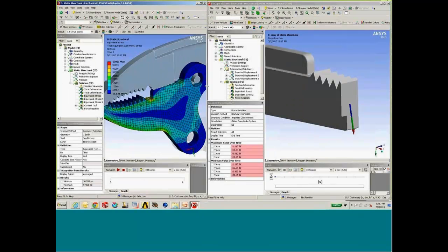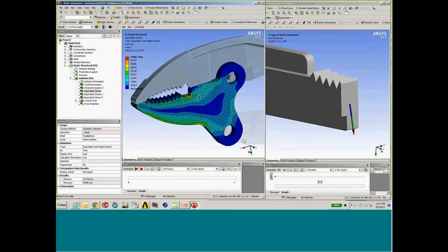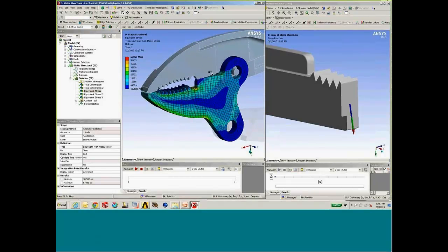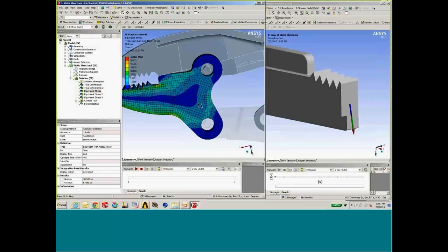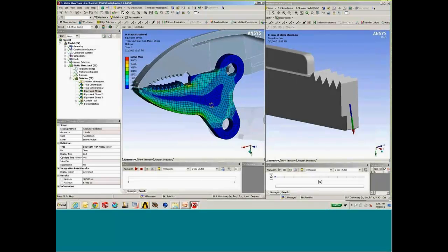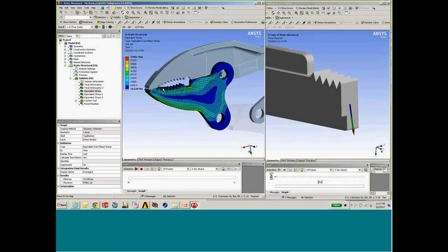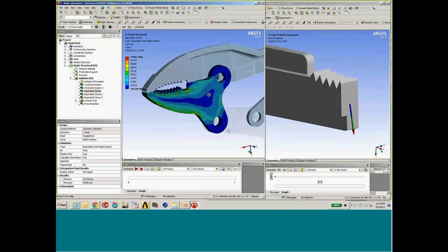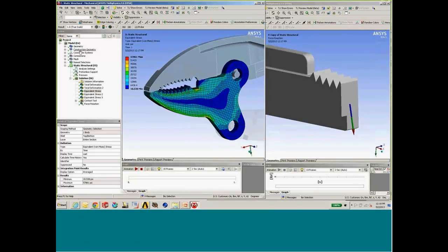Okay, well, now we have, actually, let me get a little bit bigger here. Now we have a little bit of a dilemma here, because you'll notice that there's no mesh boundary in my global model that matches the submodel. The cut boundaries in this case don't exist in the global model. Sometimes you can set it up such that that's what you want to have happen, but in most cases we don't really know where those cut boundaries are going to be. So what we need to do is find a way to interpolate the forces onto the location where we place the cut boundary. Well, we can do that at 14.5 using construction geometry.